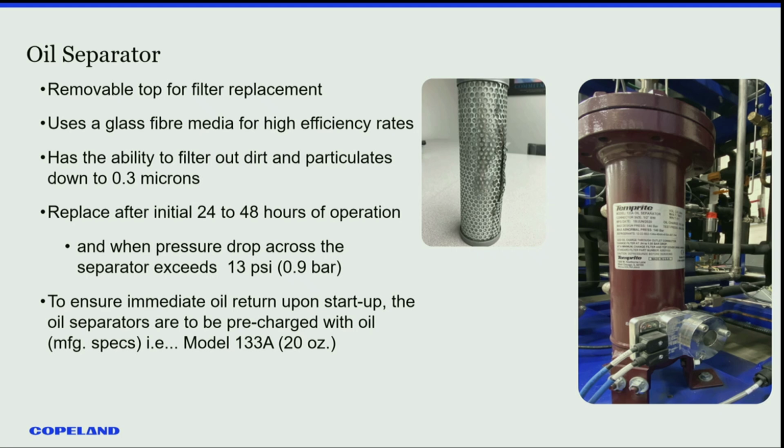Recommended pressure drops may change a bit, but around 12 to 13 pound pressure drop from inlet to outlet tells you that this thing is loading up with dirt. It's time to change it.